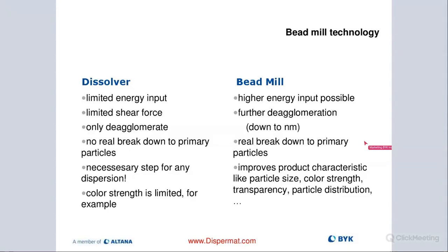If you only pre-disperse and you don't mill, you're going to have poor color development, insufficient gloss, those issues, cleanliness of shade, lack of transparency. So that's all going to be related back to just using a dissolver blade and not milling. When we are bead milling, we're going to be able to put in a lot more energy with the beads and the rotor.